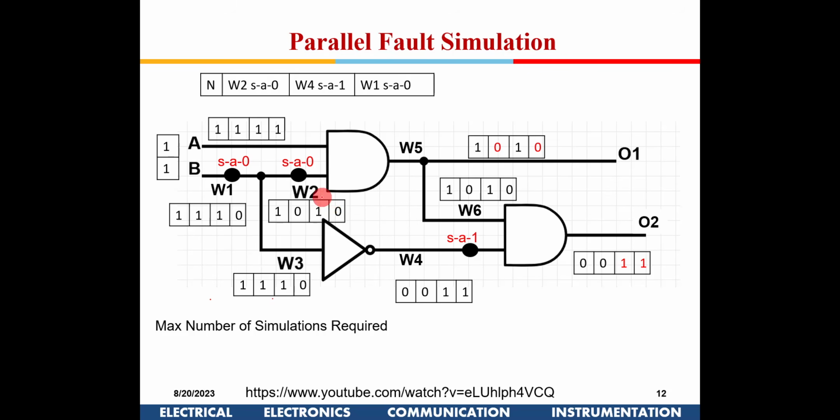When I say 8-bit processor, if I do an OR operation, bit 0 to bit 7, I do OR operation with A7 to A0, so it will do a bitwise OR. Here it is bitwise AND. All of them will be done in a single clock cycle itself. It will just do the operation and give the result. So it is pretty fast, because although in hand calculation we might do it one bit at a time, these CPUs handle all this as a single piece of information in one clock cycle. It will do the bitwise operation and give this result in one go.